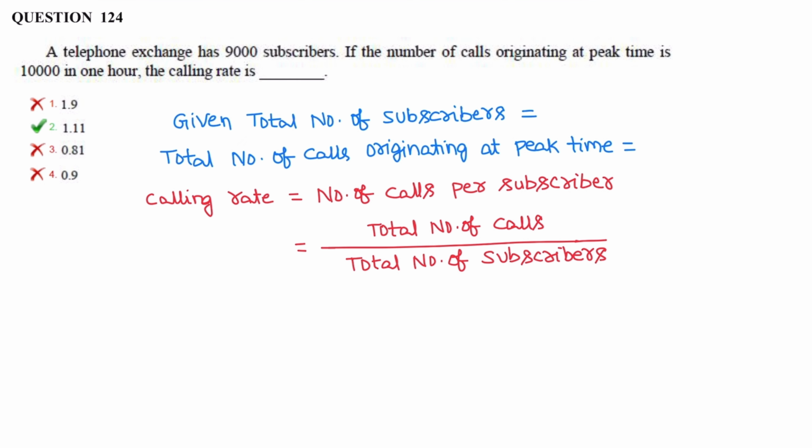Question number 125. The process to arrange the atoms in single crystal fashion upon the single crystal substrate is epitaxial growth. Epi means upon, taxis means order. Epitaxy is a method of growing a crystalline layer on a crystalline substrate, where the layer mimics the crystal orientation of the substrate.